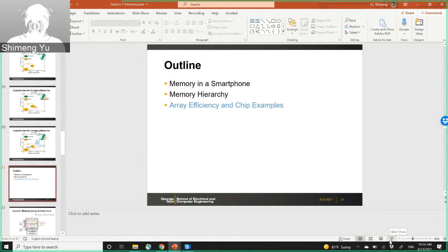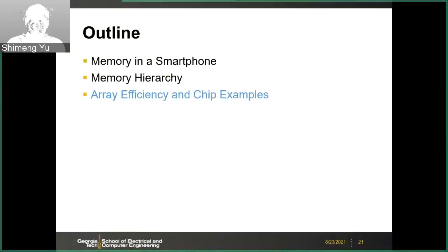So I would say for the memory system, if you stack in 3D, like 3D NAND, as we will discuss in details later, it won't help too much with your latency. Because NAND still has a long string with those transistors, the parasitic RC is still large. The long string, in the 2D case, is a long string horizontally, and when you stack into 3D, then it's still a long string in the 3D dimension. So the NAND speed will not improve too much, and the DRAM is a different story.